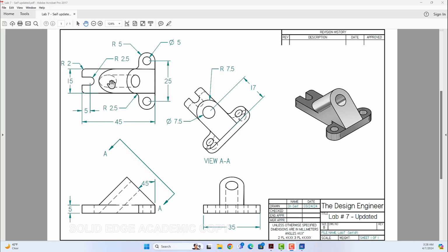If you look carefully at the main projections, I have the top view, the front plane projection, and the right side projection. And this is an auxiliary view. As you can see, I'm looking at the part at a 45-degree angle to the surface here, which is in this direction.